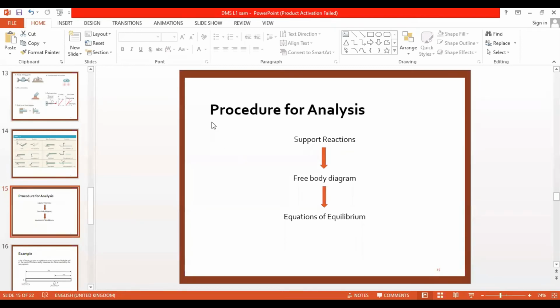So the question will be given in a written format. Sometimes there can be diagrams, doesn't matter. If we don't have the diagrams, we can draw the diagram. Then apply all the forces and lengths and whatever data is given. Then draw the free body diagram if it is asked on a particular body. Then use your equations and solve it, right?